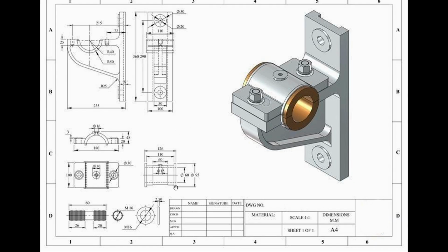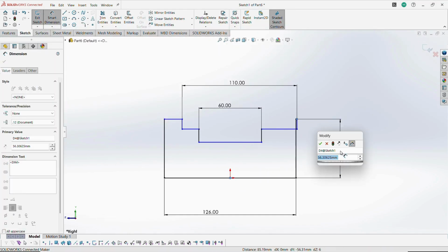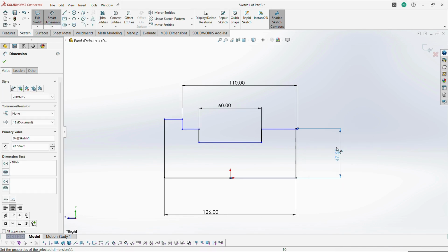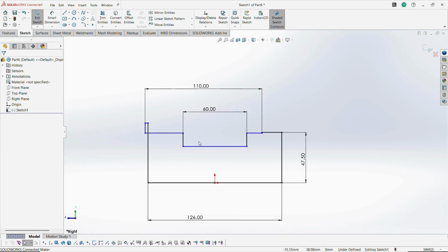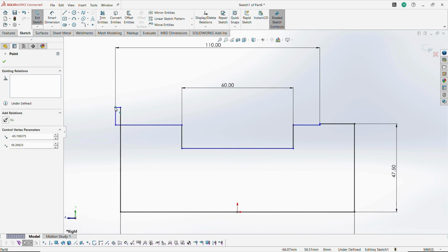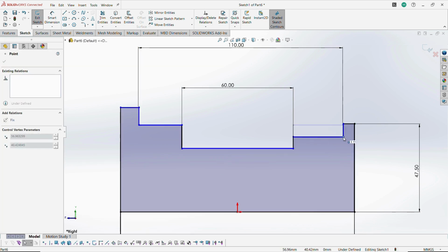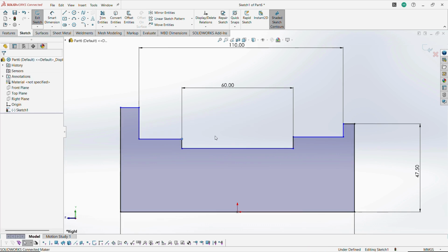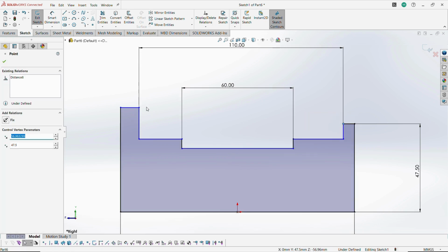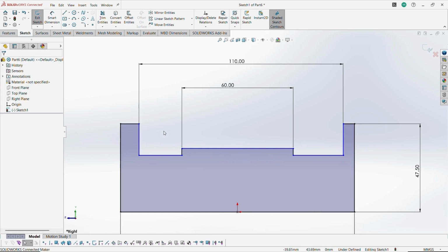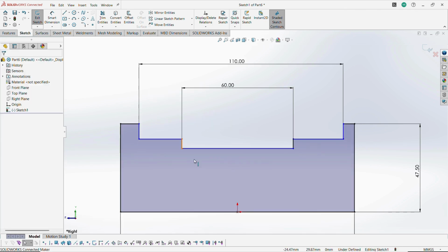Then what is the vertical dimension? Total is 95 mm. From half of its value, you are going to achieve 95 divided by 2. Let's place each of its points relative to it and form a proper closed portion. Look at it, one point is offset next to another. If you want to close this properly, there are a lot of steps, we need to constrain it because already the endpoints are not constrained to each other. So first select all points and use a horizontal constraint to fix it equally. Afterwards, again place my cursor and move these profiles to the top of its portions.